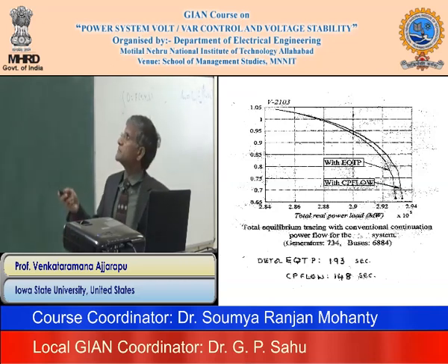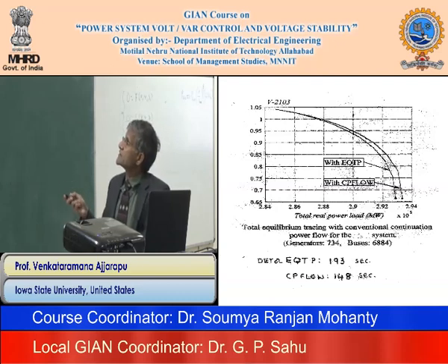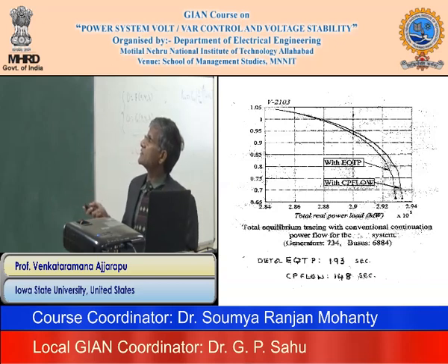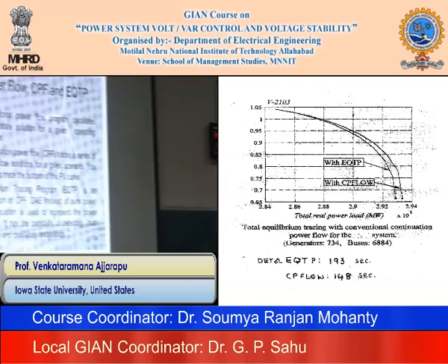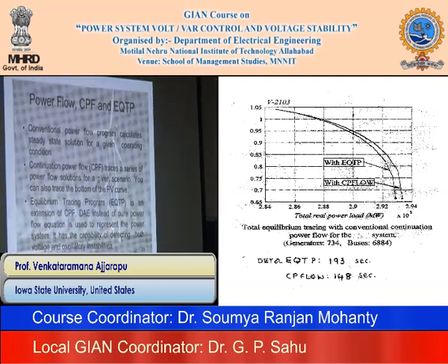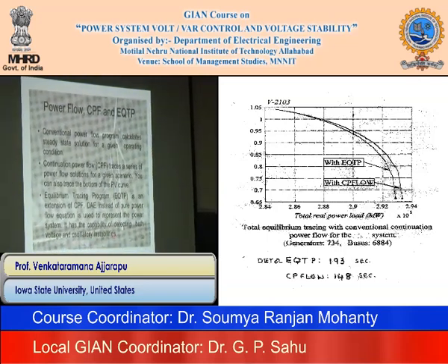So this is the summarization. Conventional power flow calculates the steady state for a given operating condition. Continuous power flow traces a series of power flow solutions for a given scenario. You can also trace the bottom of the PV curve, and the equilibrium tracing program is an extension of CPF. DAE, instead of the pure power flow equation, is used to represent the power system. It has the capability of detecting both voltage and oscillatory instabilities.